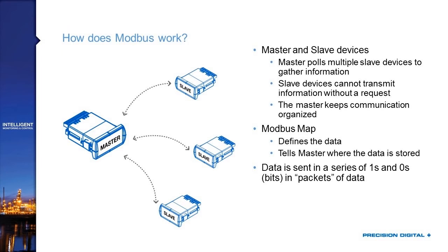So that's what Modbus is. It's a master organizing communication to a bunch of slave devices on the Modbus bus. And the Modbus protocol defines how you structure that language they're talking with, the zeros and ones, what the language looks like so that they all know how to react.